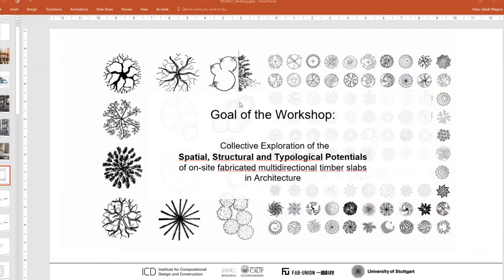Yeah, I did that because, I mean, I think they could be a little bit offset inside as well. Like they're too much at the edge. But basically, if we go to the plan drawing, because of the overlapping of the roof canopy of the first floor and the second floor, the floor area on the first floor is very limited. If I have columns at the center, that would disrupt the space. So just to optimize the amount of usable space, I try to put them at the corners.